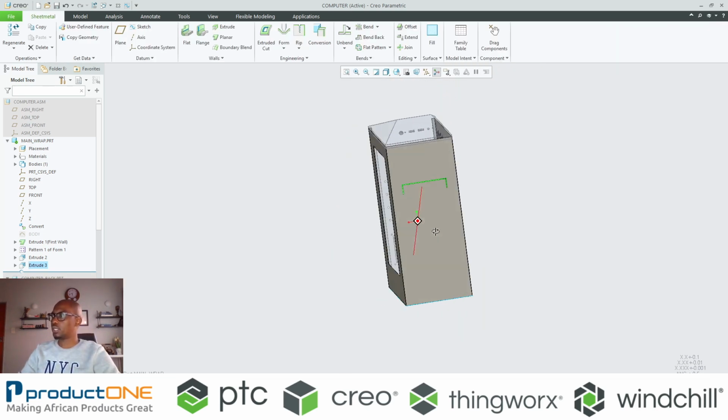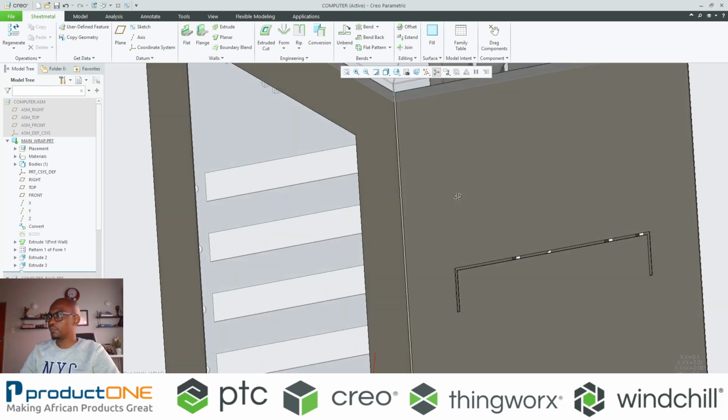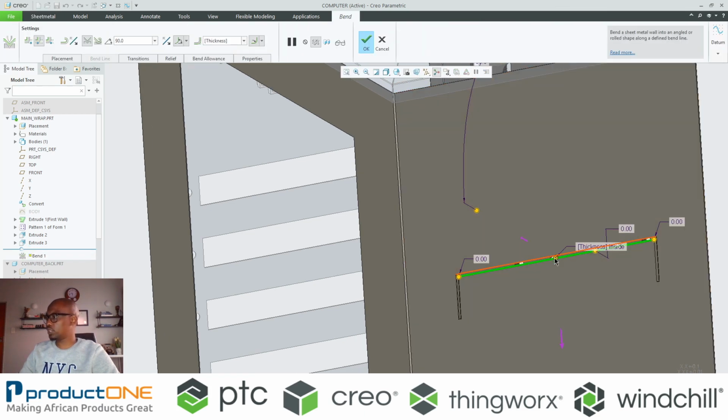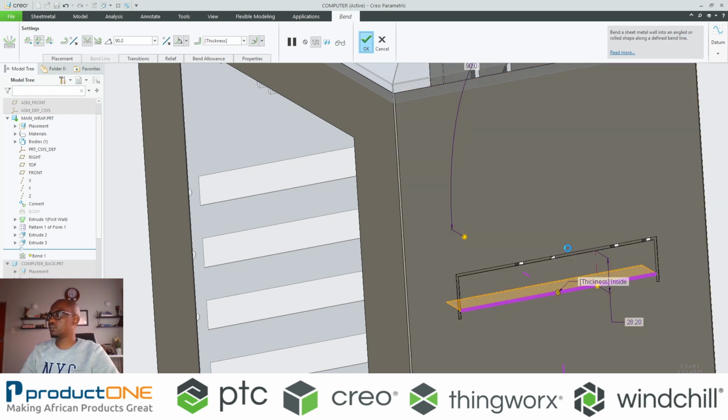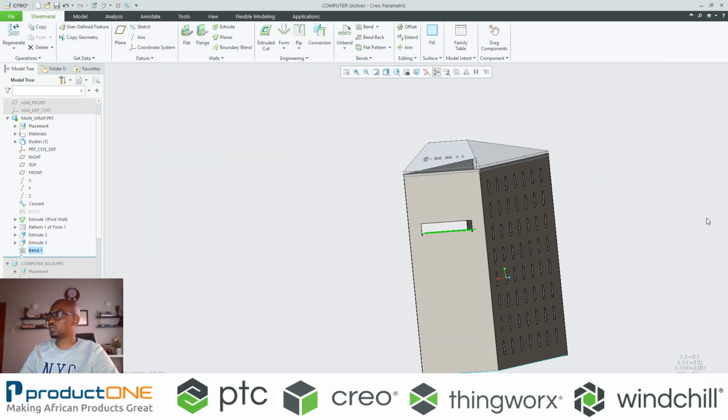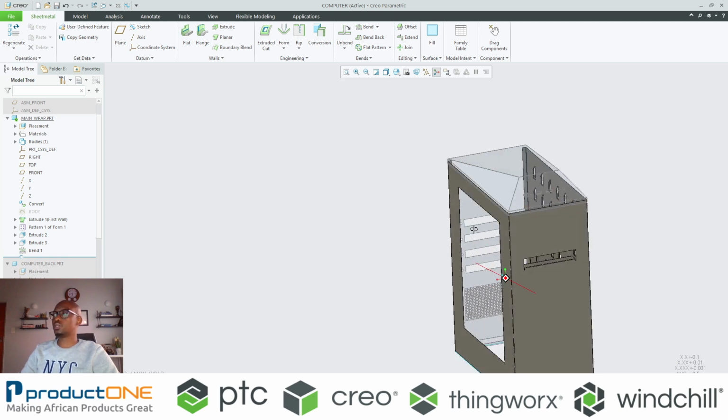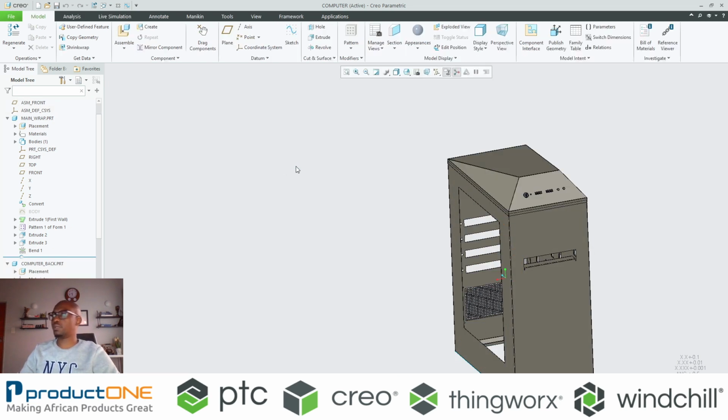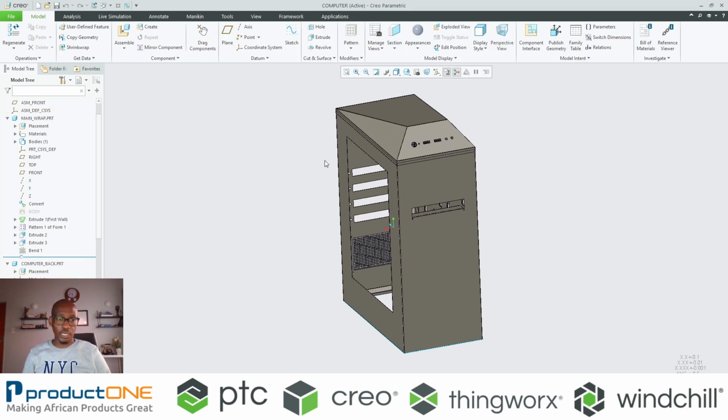So what I'm going to have now is removing material, utilizing a thin plate or thin cutout. And what I like about this is I can actually say I understand that I've got this cut here, so I can say I want to generate a bend, and by just doing that, there is my sheet metal bend on this product. So this is the power of sheet metal, whereby you're utilizing constant thickness plates to generate complicated products such as your toaster or whatever you can desire.